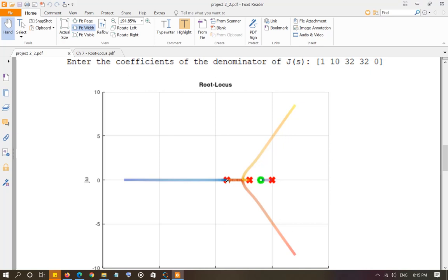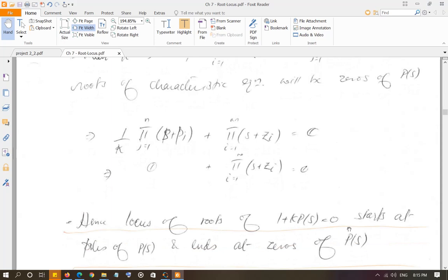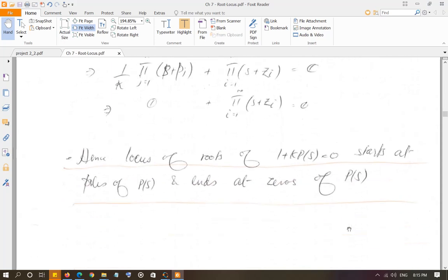And then again starting from this, since there are two poles over here, heading towards infinity again where there's a 0 sitting over there. This thing we're going to discuss pretty soon. So again, your step number 1 is find all the zeros and poles of PS and put them on the S-plane. That's step number 1.